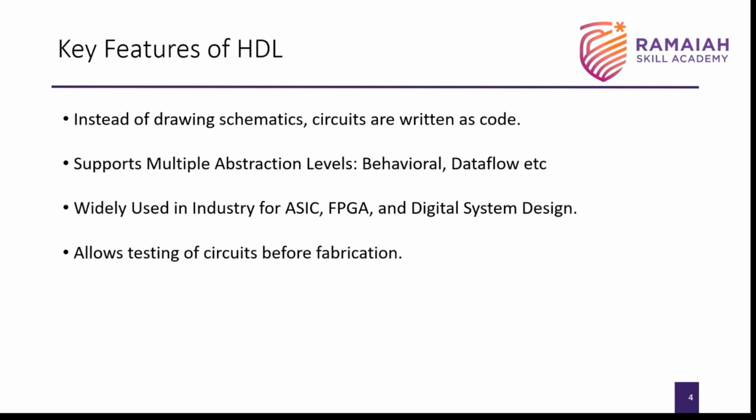It also allows testing of circuits before fabrication, because once the circuit is fabricated and you have the chip with you, then you cannot do anything if it goes wrong. Before it goes to fabrication, you need to make sure that your circuit is free of bugs. That is where hardware description languages help you in testing the circuits before the fabrication.